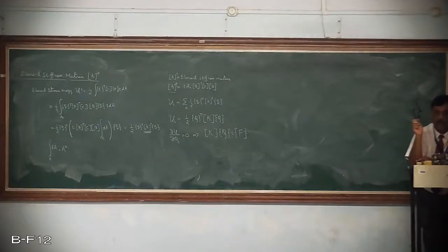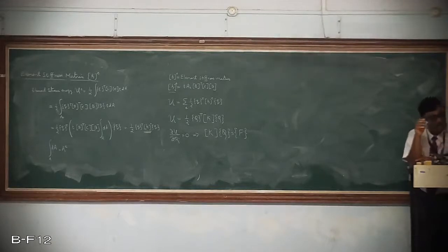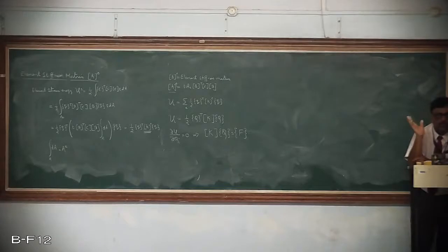Then it is banded, or it is called a banded matrix, actually a sparse matrix, banded or sparse. Banded means we minimize the spaces available in the computer. We should occupy minimum spaces for the locations. If you look at the global stiffness matrix, there are a number of zeros, so to save storing these empty spaces we are going to make this banded, and we want the semi bandwidth of this global stiffness matrix.